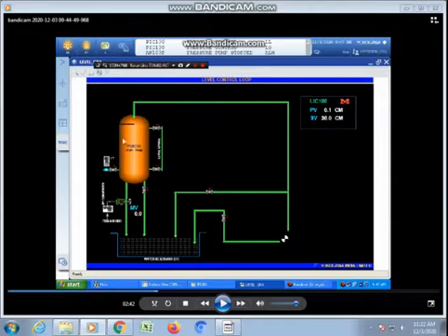The tank level is measured through this level transmitter. Now how will you maintain the level in this particular tank? By this control valve, which sends the water outlet from this tank. By the I to P converter connected from the DCS, we will control the valve operation, and the level inside this tank can be maintained. In order to avoid any impeller problem in the motor pump, we have a bypass valve also.